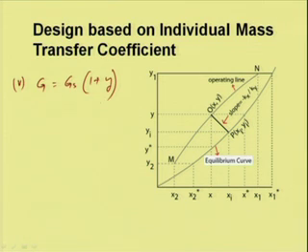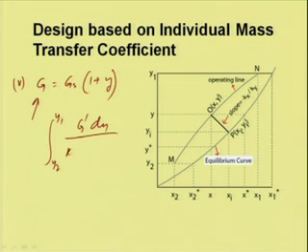And we can check how G is changing at every point. We will come later to how to calculate the area under the integral, that is from y 2 to y 1 G dash dy by k y a (1 minus y) (y minus y I). So, we will come with an example to calculate this.